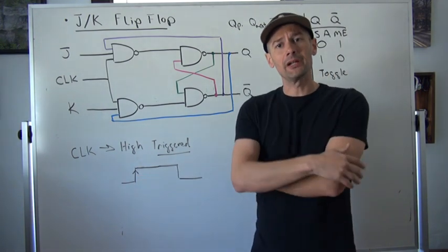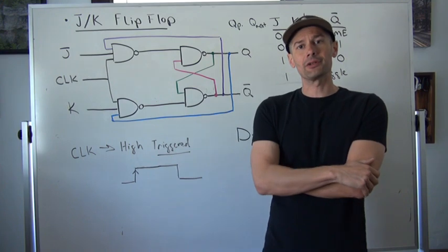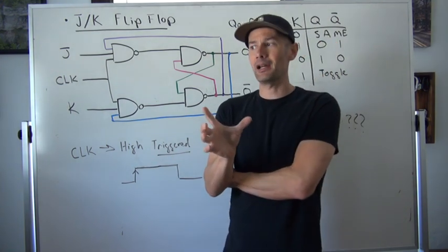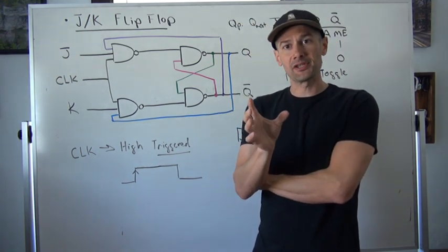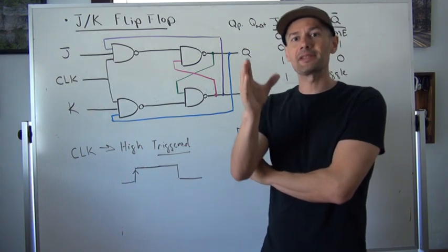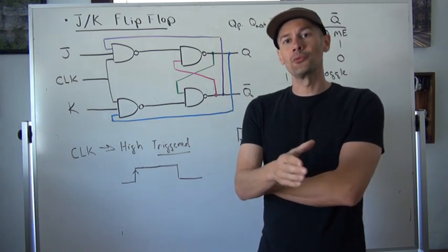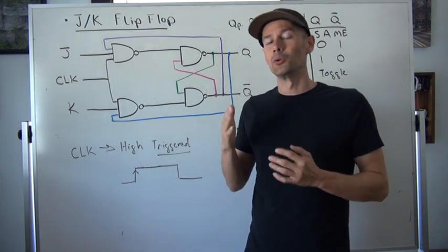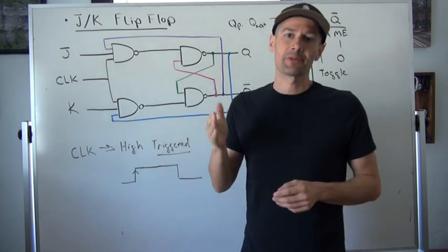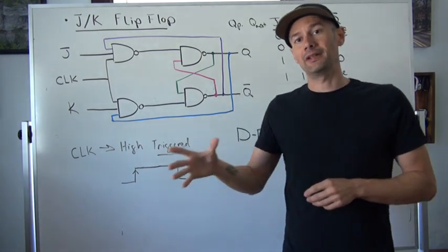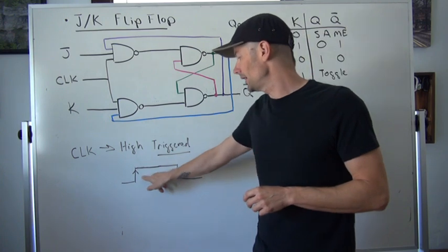The reason we want edge triggering as opposed to just an enabled high cycle is that a synchronized system allows outputs to change only at very specific points instead of any point during the high cycle.